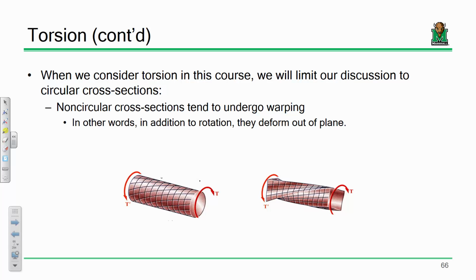If you have a steel beam and it's being bent, the top of the beam is experiencing compression, let's say, and the bottom is experiencing tension. Anything that's in compression likes to buckle, but with beams like I-beams that are being bent, when part of the beam is experiencing compression and part is experiencing tension, there's a stability issue. It doesn't really know how to handle it because part of it wants to buckle and part of it doesn't.